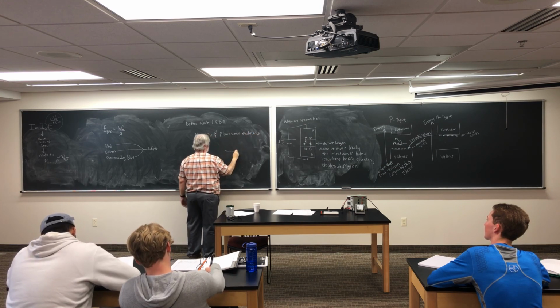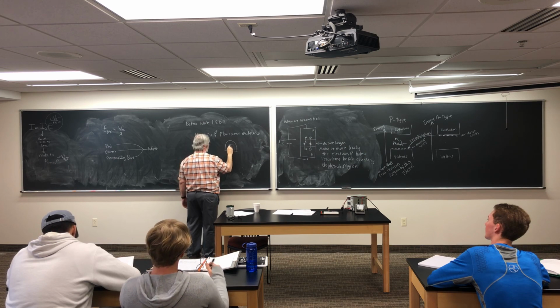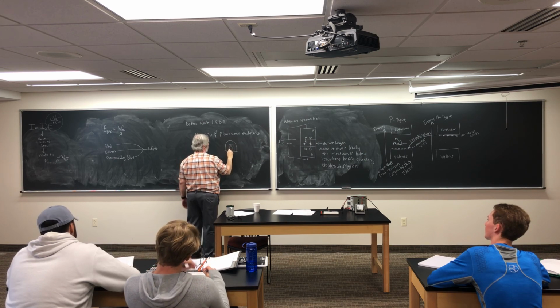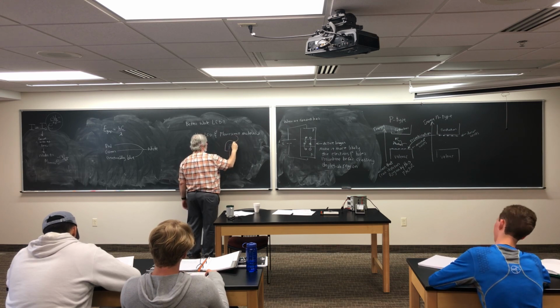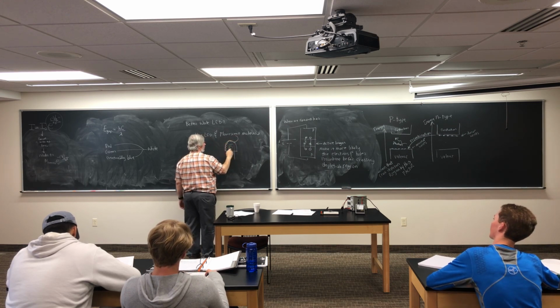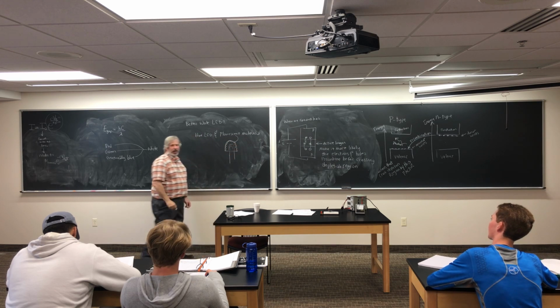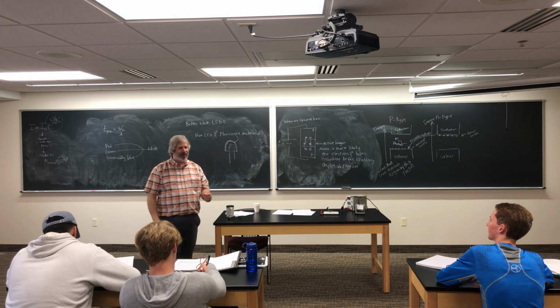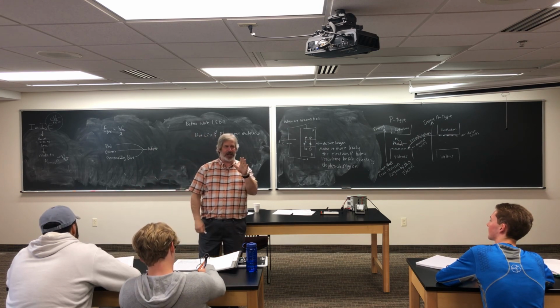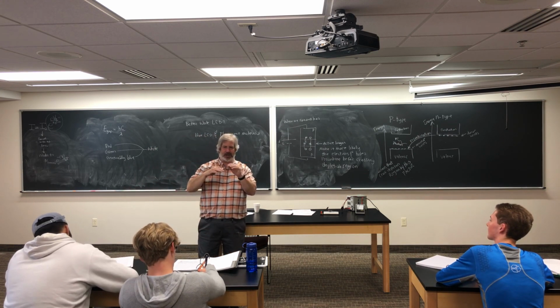So you have that capsule, you have your blue LED, and then you have this fluorescent material that coats the inside of that. So what does a fluorescent do, we talked about fluorescent briefly. You hit it with light, then it creates light at a longer wavelength, right?